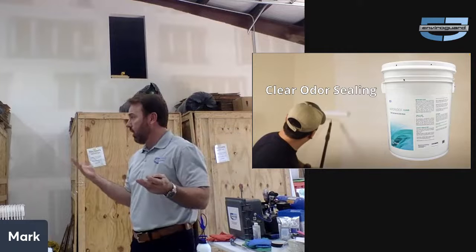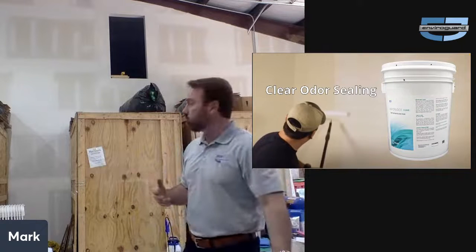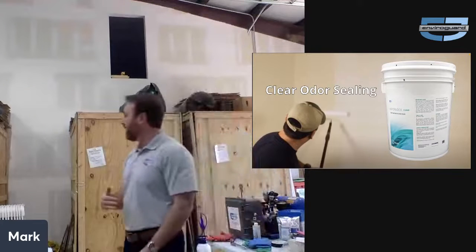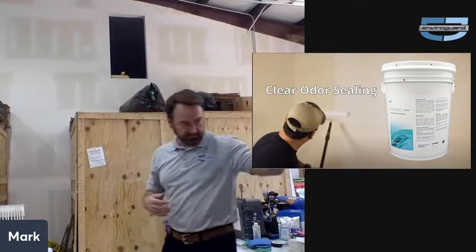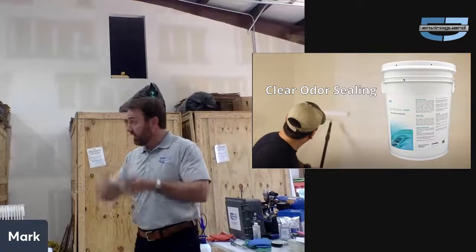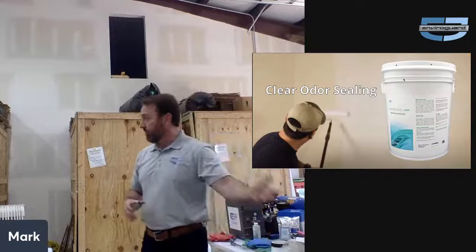Why do all of the tear out and things of that nature if we can just seal those walls up fairly easily with a clear product that goes right over the paint that's already there, right? So after a wipe down of those walls to remove any soot deposits and those sorts of things, probably with chlorine dioxide as well to mitigate any of the odor that's just sitting on the surface, we can clear coat that with Vapor Lock Clear.